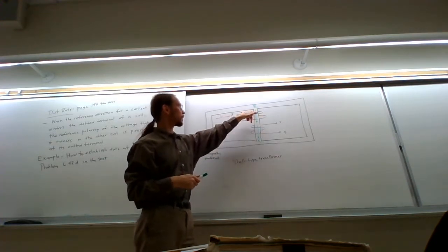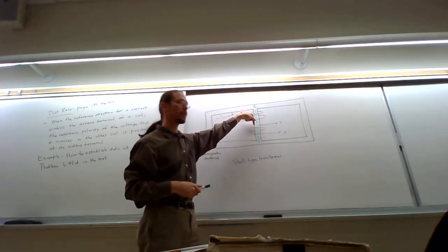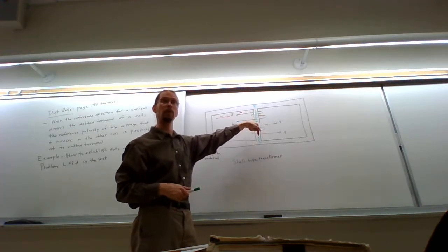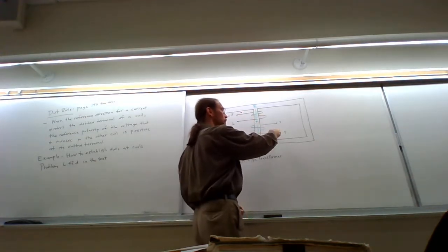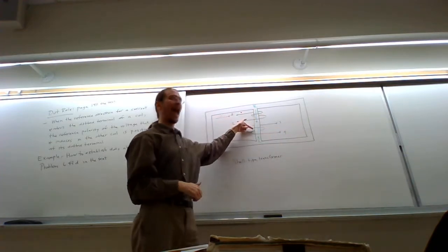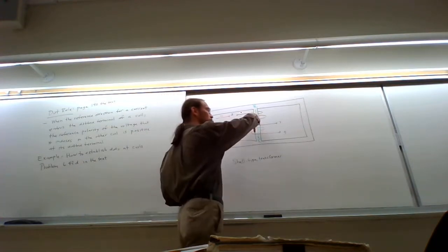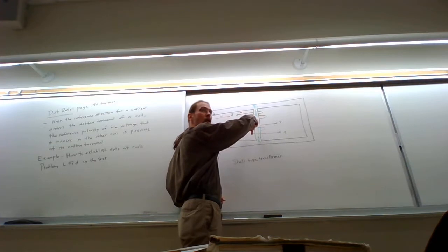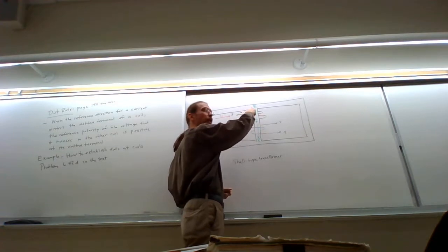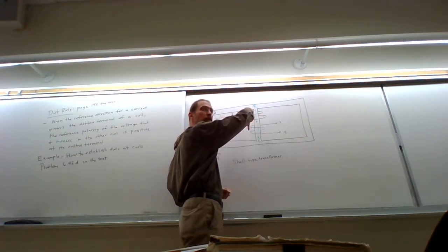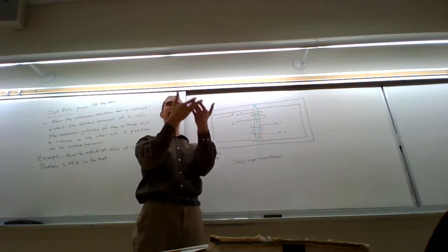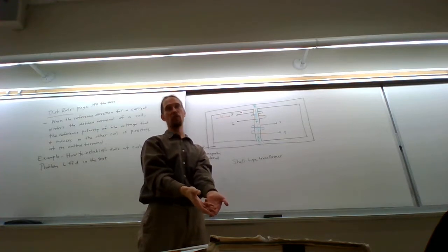Now, this over here, again, is generating a magnetic field down here, going down this way, and it's going to generate the magnetic field coming down this way through the second coil as well. Now, over here, depending on where I feed in an entering current, it can either add to the magnetic field if the magnetic field produced by the second current is in the same direction, or it can subtract from it in the sense that it would go in the opposite direction. The one where it happens to add, as I feed in the current entering, that's where my second dot is going to go, because superposition is going to increase the flux, which is going to increase the voltage, right?